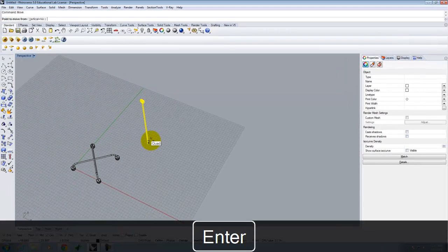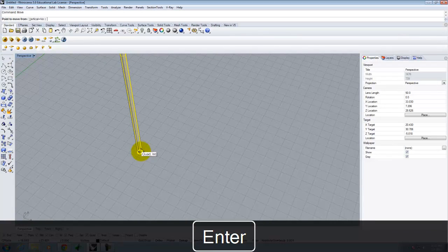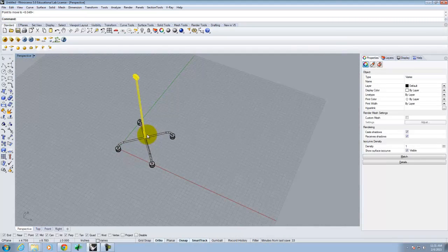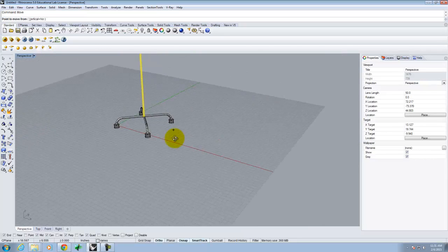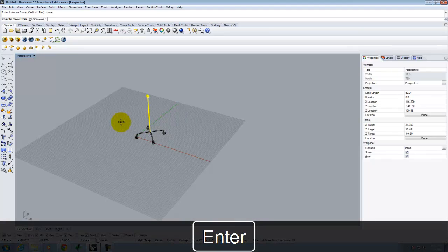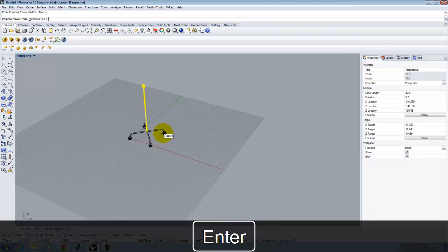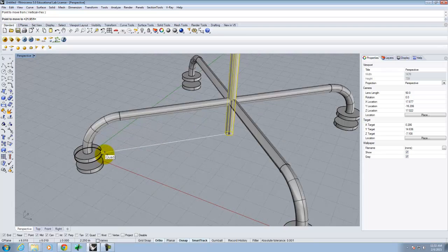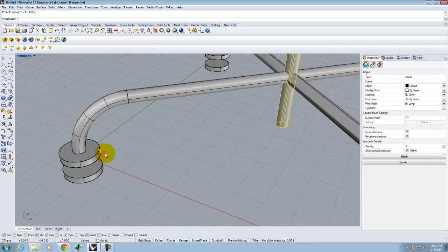But when I move this from here, if I use snap and snap to that midpoint, it's a little bit too tall. Okay, so I still need to move it down vertically, and so we'll go ahead and use move, and then I'm going to type V for vertical, and I'll pick this, and then I will use my quadrant snap or my circle snap to get a reference point right there and move that down.